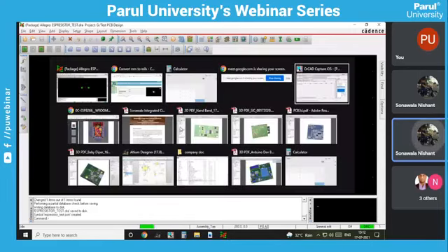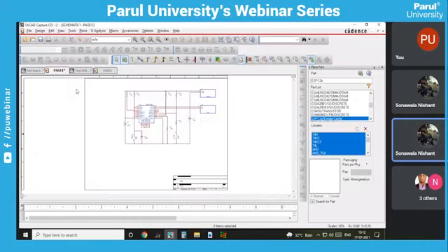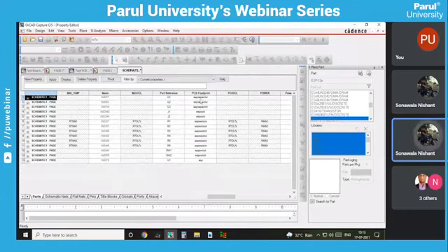We have already mentioned all the footprints in our schematics. Select all the schematics, right click and then edit properties. I'll show you that I have already mentioned all the footprints. This is the PCB footprint we have assigned to all our components. For capacitor we have the ESP capacitors, for J1 and J2 we have the ESP connector, for resistor we have the ESP resistor, for switch we have ESP switch, and for U1 we have the ESP. Now simply save it.